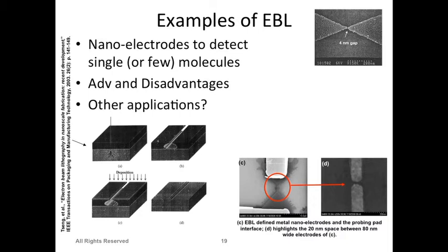So yeah, in our case, what we did is first we used TMAH to make that kind of a window structure. Let's say this is a wafer, so we open a window, so it goes all the way through, deep, until we etch the whole wafer through. And on the other side, there was just a thin membrane of silicon dioxide, because the TMAH doesn't etch silicon dioxide, so it will stay there.